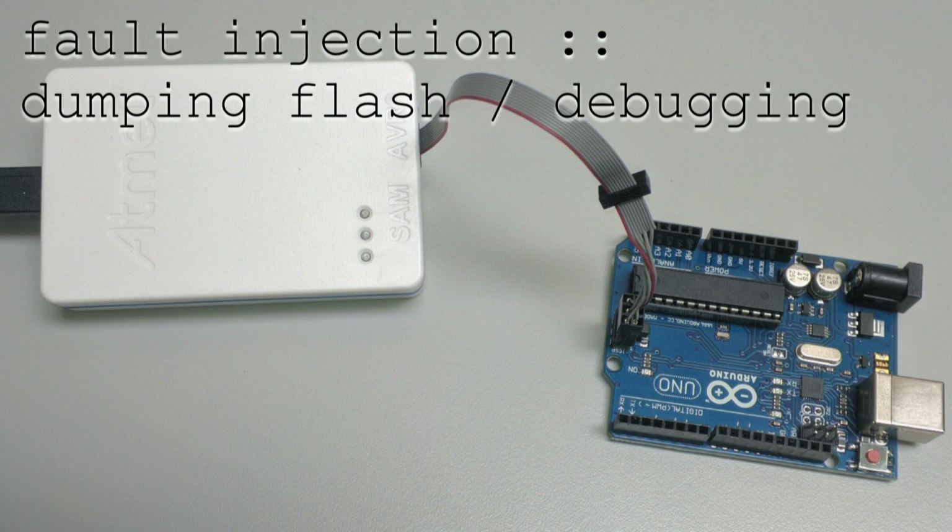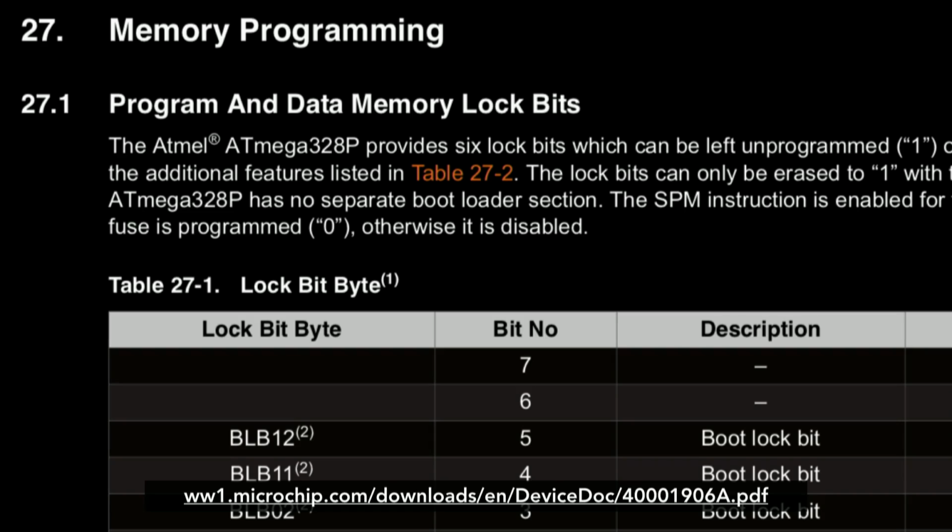Now, that itself is not an attack. These are intentional, right? These chips are designed so that you can access the data inside and verify whether it's correct or not. Except for the fact that they also have these features called lock bits or fuses. And these will allow the designer to lock their firmware, their memory, and the idea is to prevent other people from being able to access the data.